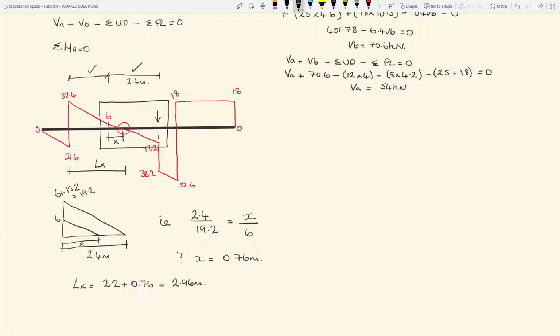Right, in calculating the bending moment at any particular point along the beam, what you need to remember is that for a simply supported beam, any load applied to a beam that gives a sagging of the beam, so the beam deflects down and the bottom is in tension, any load that gives that is positive bending.